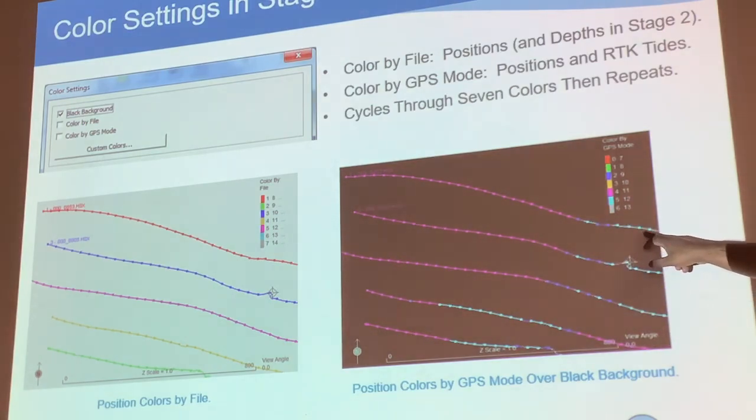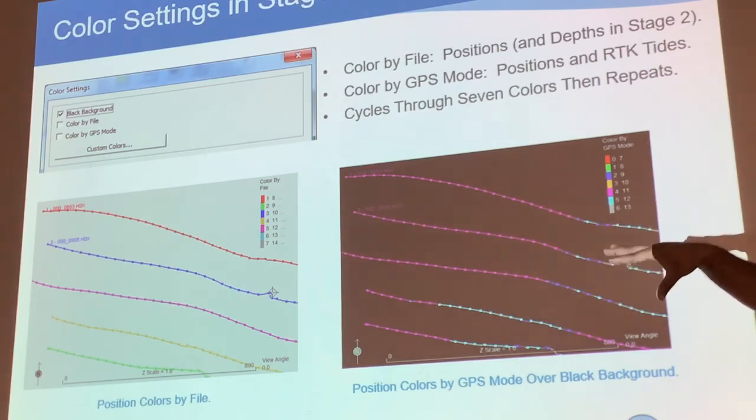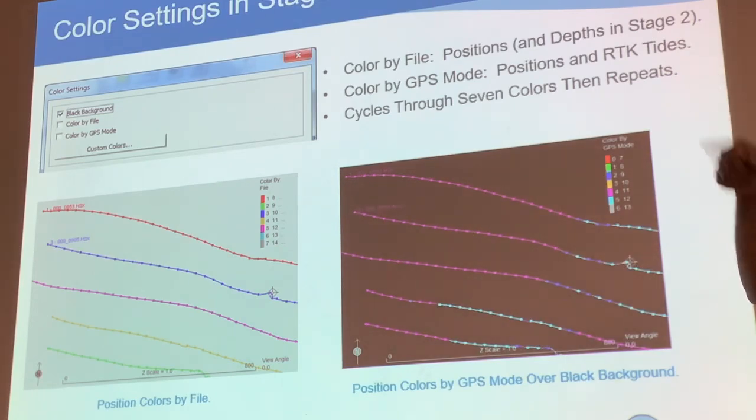Over here, it goes to 5, that means it's low accuracy. So it shows you that during your survey, half the survey is actually low quality. So the position, you see over here, it jumped. It's not accurate. There's actually a table, you can check the quality.